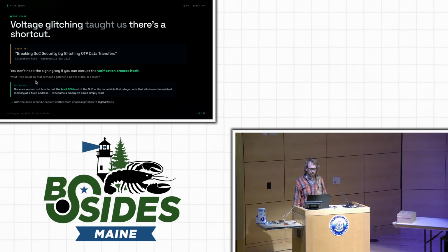He demonstrates an entire automation around using an FPGA board to essentially blast the SoC with electromagnetics at different points along the X, Y, and Z while powering it on. And what he finds is, while it's not consistently obtained, it's easy enough to obtain via a glitch to bypass the secure boot enough to study the device.